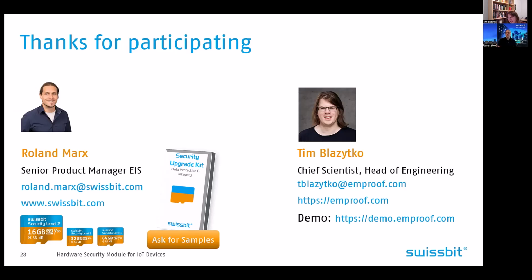So yeah, sure. If you go to our website, emproof.com, you will see that we have a product called Nyx. Nyx is basically a binary rewriter. So we don't touch the source code, we don't touch the compiler, we don't touch anything in between. What we do is we take the final binary or the final firmware, which would be flashed onto the device, and post-process it. We have a binary-to-binary translator, which means we read in the binary, analyze it, add some protections, and then spit out a hardened binary.